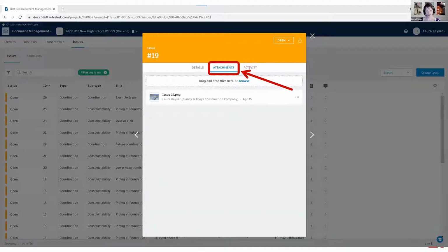Like I said, I'm then creating a screenshot, and I am using the attachment feature. So here I am back in the web interface. You can see my list of issues back here. I can create attachments, and I can drag and drop different file types into here. That way, when I'm producing my report, I have that image of what the actual issue looks like with everything hidden and all my visibility settings and all that good stuff.